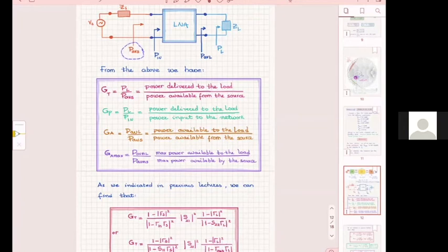We have already altered that by the considerations for minimum noise, for stability, for gain, or a combination of all of those. So GP is really what your amplifier gives. If you were to go to the lab and measure, GP is the real thing to measure because it really tells you how much goes in and how much is delivered.